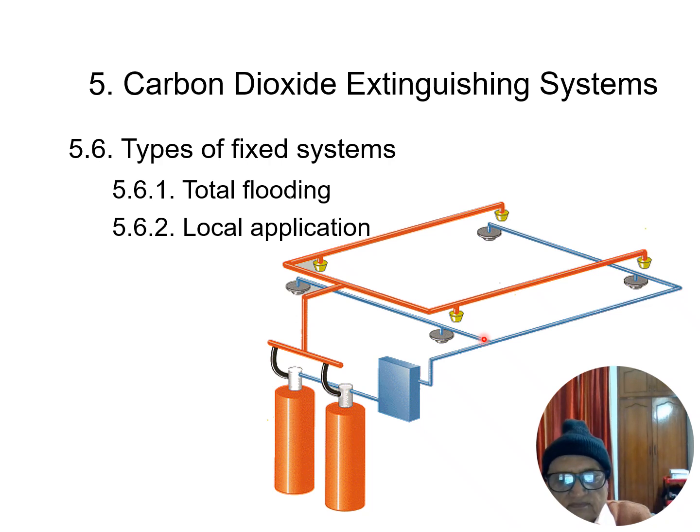These are the fire detectors, 1, 2, 3, 4, and these are the nozzles through which CO2 will get discharged into the system, and this acts very fast. Within a second, it will flood the complete room and extinguish the fire.